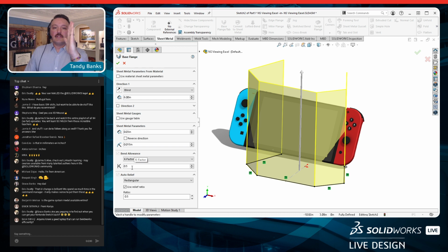When I take something that's flat and I bend it, there's a neutral line, and depending on the material, that's affected. Like I said, with steels and some grades of aluminum, it's a smaller than 50% K factor, and the reason why is we compress less and stretch more.